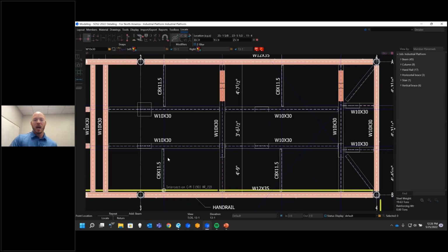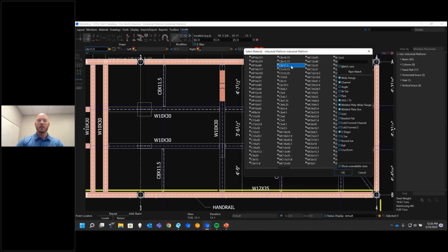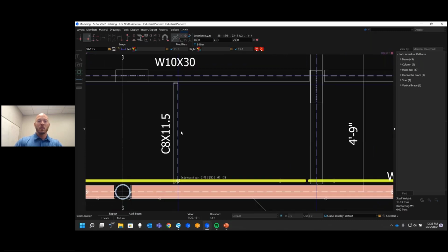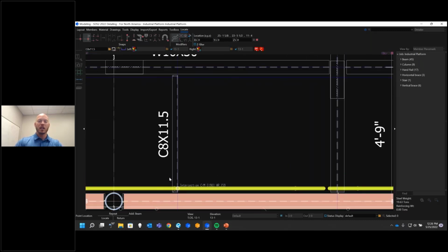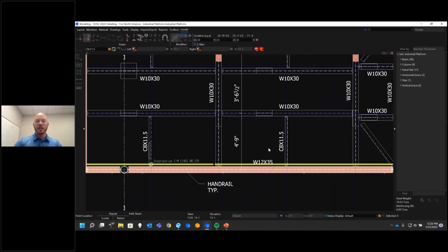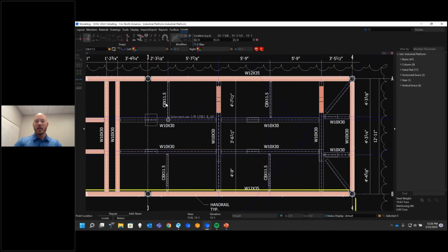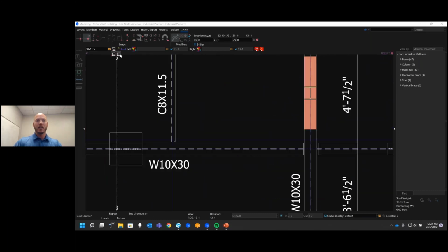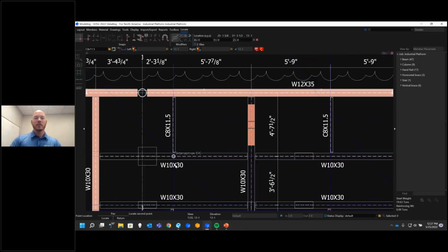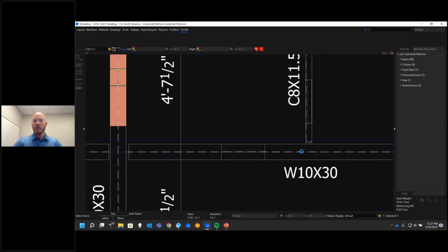And then I can put in my channels here. So my channels, I'm going to have a little extra to worry about because I got to worry about the toe direction. Okay, so if I'm working with the left-hand rule, the toe's over here, the toe direction is going to be out. And I do have a little option here for the toe direction out. Okay, so I get that one in there. Middle click, repeat that one. And then I can come up here to these others. Looks like these are toe in. Same over here.